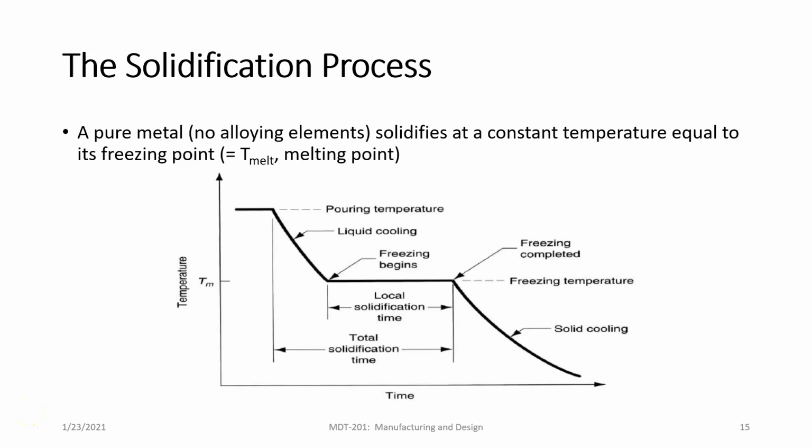Okay, let's start part two of our introduction to casting and molding. We left off part one talking about how we get the liquid metal into the mold, and remember that there's basically two ways: we can fill the mold fast, or we can fill the mold slowly, and both of them have trade-offs, right? Filling the mold fast is going to allow the liquid metal to get into all the nooks and crannies, and the metal is not going to solidify prematurely.